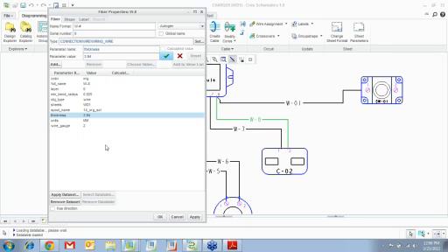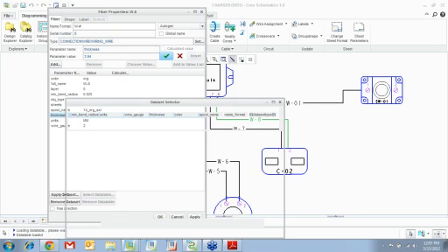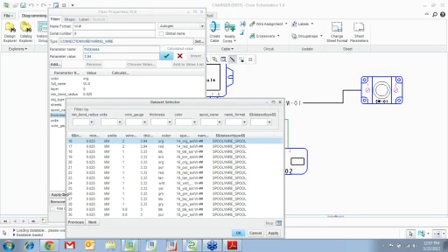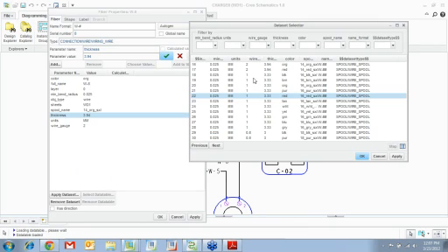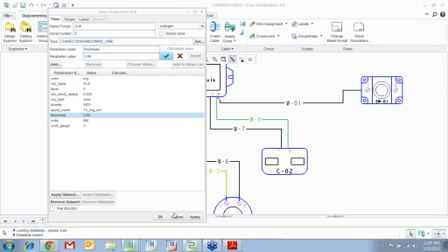Now instead of manually entering all these values every time you create a wire, you can load a bunch of Excel files as data sets. Once you have that, you can go to a data set, apply a data set, and then you can pick whatever you want. Different color, different wire gauge, different thickness, and you can say okay, and that will be applied to that particular wire.